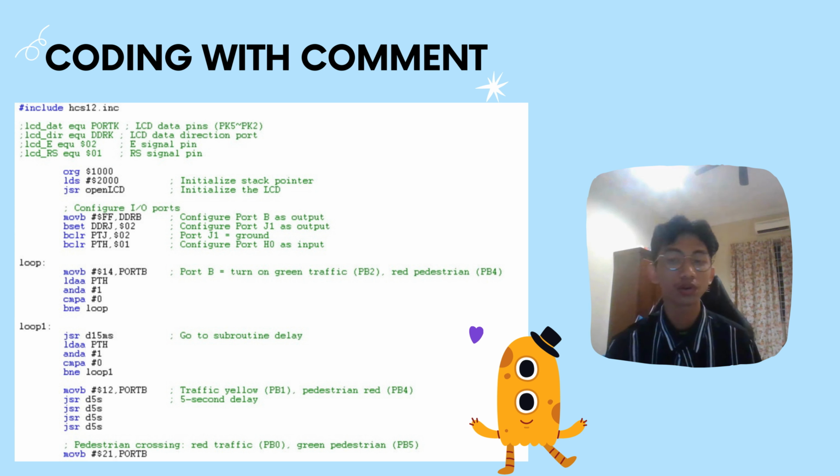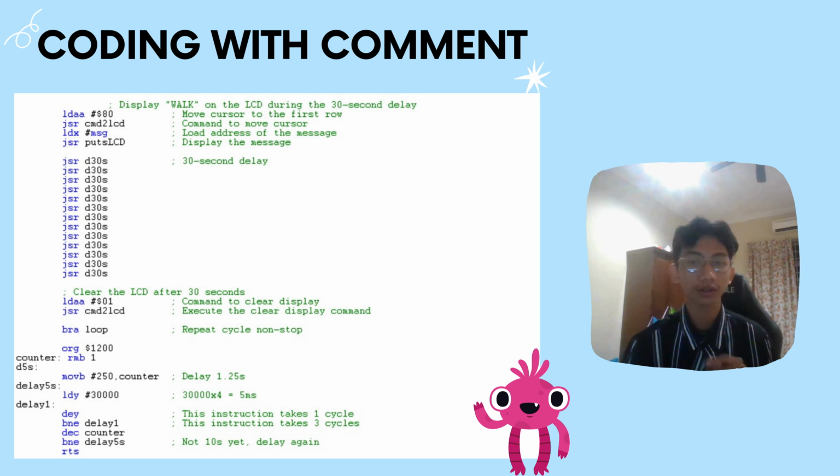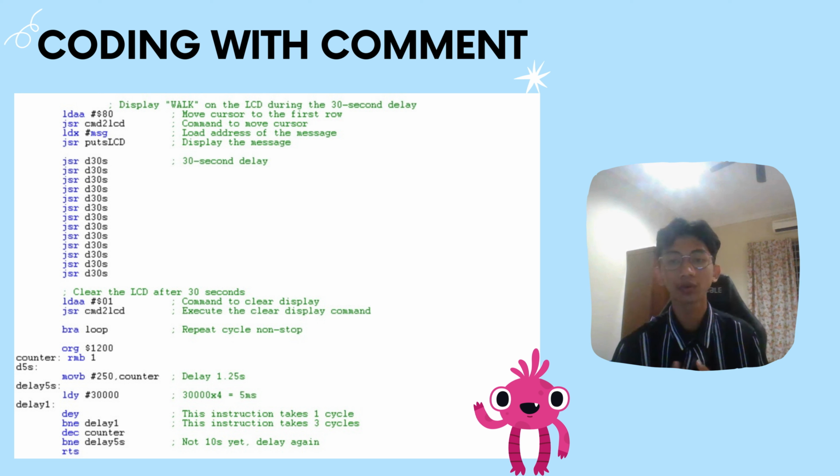The traffic light will show yellow for the road and still red for the pedestrian for 5 seconds. After the 5-second delay is where the pedestrian can cross. So LED on port PB0 will turn red and LED on port PB5 will turn green.